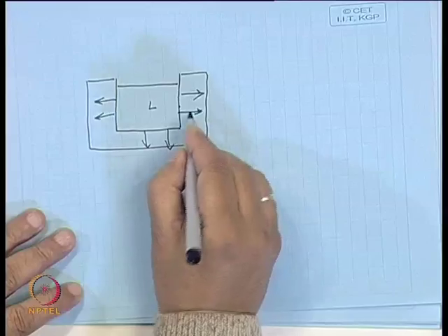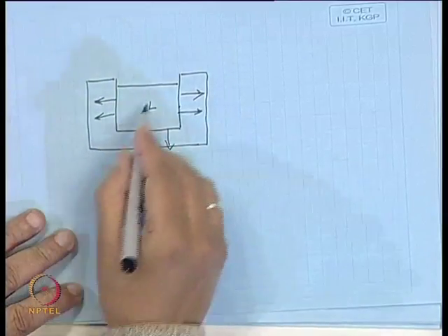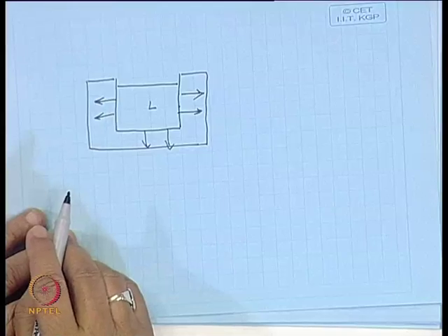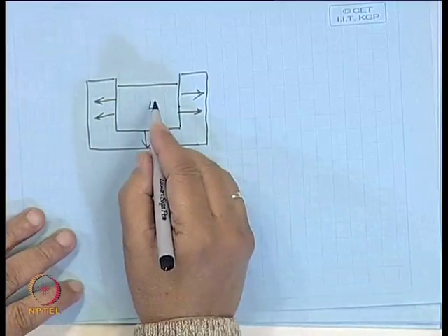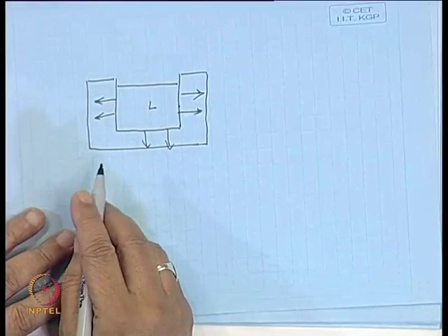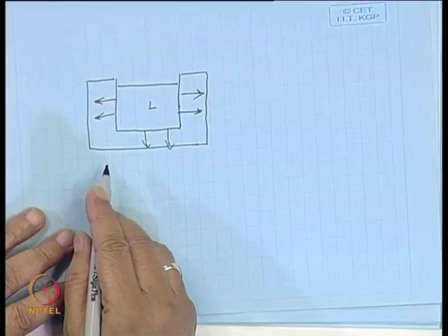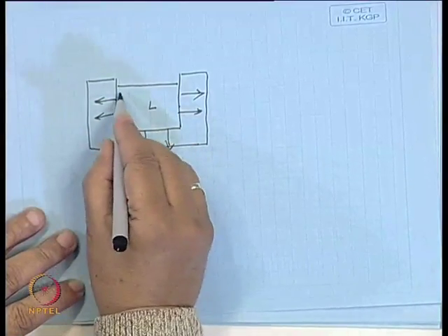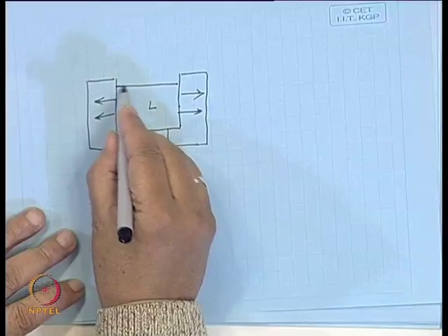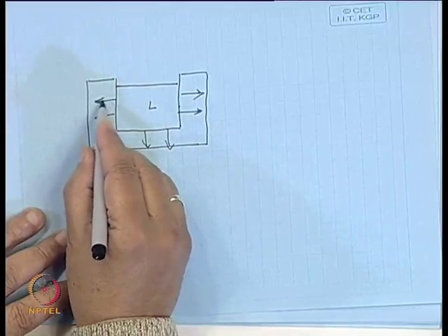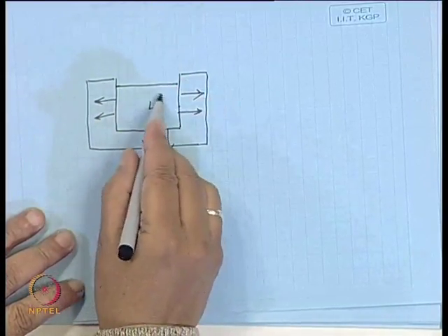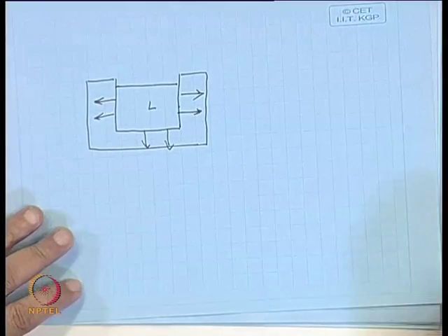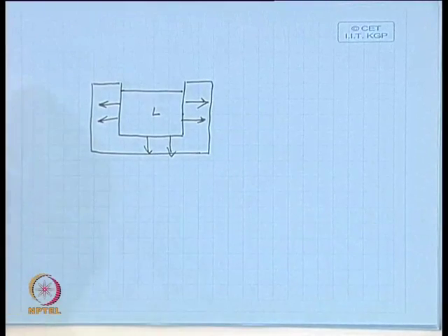The way that heat is extracted will determine how the structure will form, and we have also seen that for solidification to start, some amount of supercooling is necessary. So, the way the structure forms will depend on the way the heat is extracted from the liquid. Let us look at this in a little more detail.